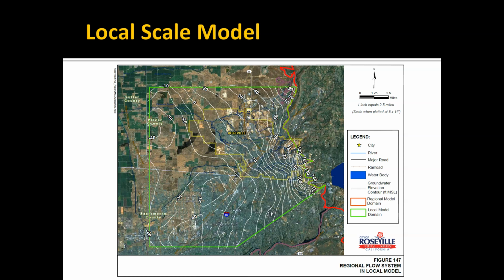We even got some telescopic or regional to local grid conversion. So hopefully now you have a little better appreciation of boundary condition selection and some of the options available to you, and you should be well suited now to start digging into your projects and coming up with good boundary conditions.